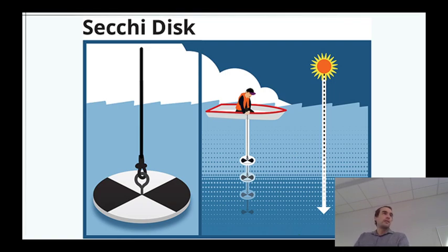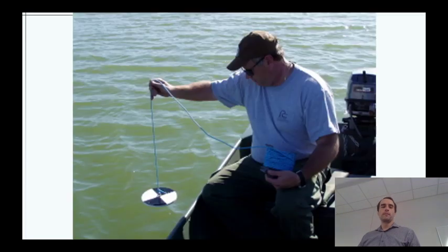If you want to measure this, at least in natural systems, a lot of times what you use is this Secchi disc, or however you say that. And essentially, once you can no longer distinguish the lines or have clarity between, you can kind of measure that distance, how far you can see a standard object like that as an example, and that gives us some, it's called nephelometric turbidity units.